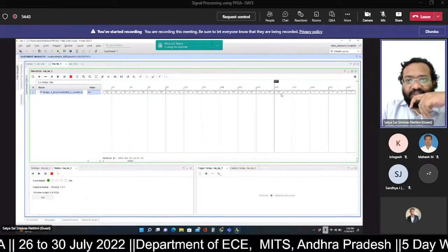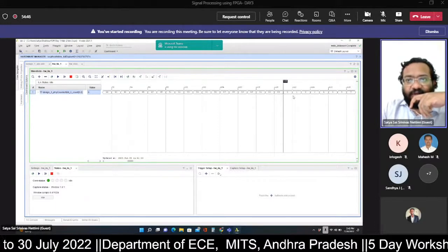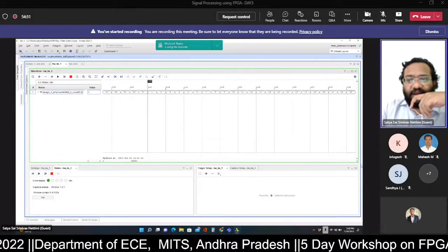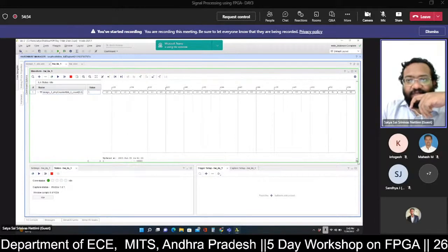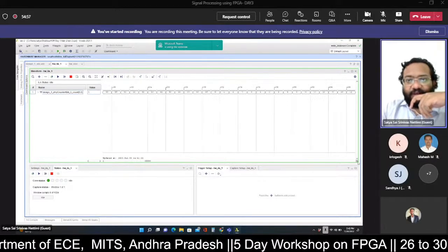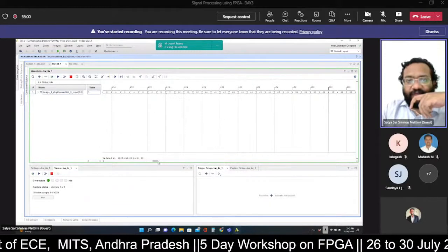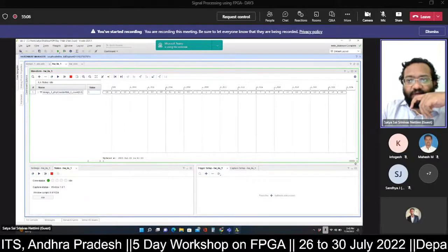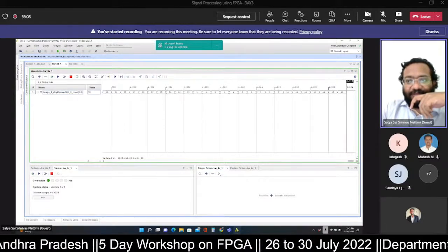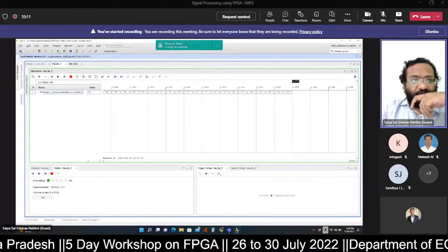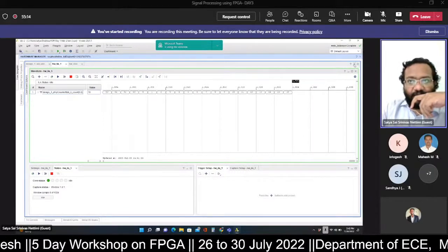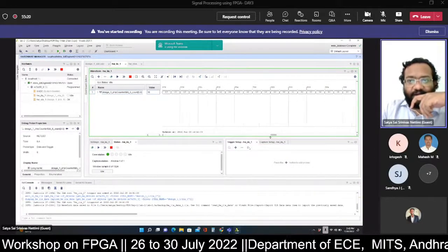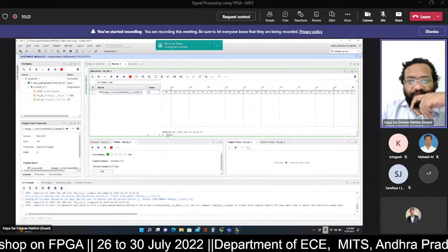Once the counter has reached the maximum, again it is reset to 0. Again the sequence continues 0, 1, 2, 3, 4, 5. Since we made enable high continuously for all the time, this sequence is being repeated continuously. So the counter is freely running all the time. And I told you it will capture only 1024 samples. That is because this ILA IP core is configured with a default memory depth of 1024 samples.